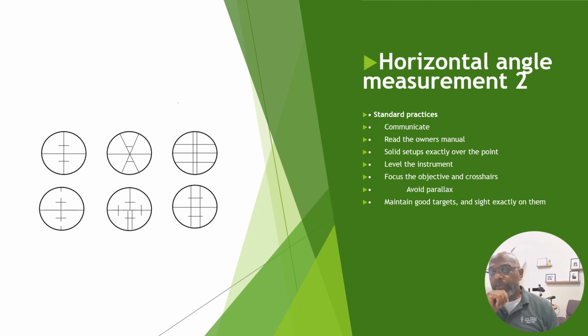Focusing the crosshairs will often be necessary throughout the day, because the human eye tires, and as the day progresses the ability to focus changes. If you're staring at something long enough, your eyes will have a tendency to adjust to that sight, so you might need to take a break, or of course refocus so you will be able to see what you're looking at.